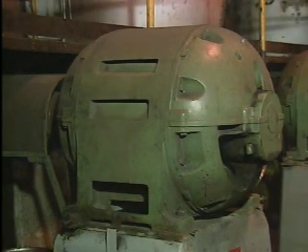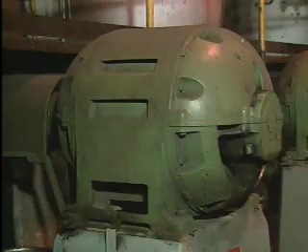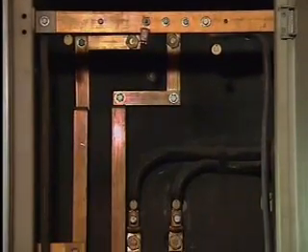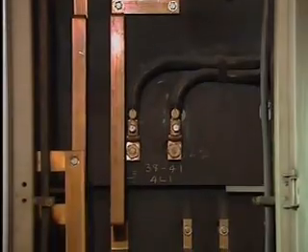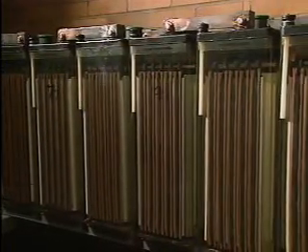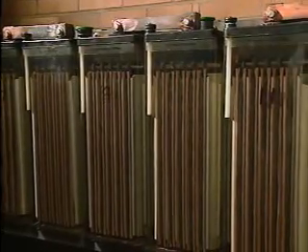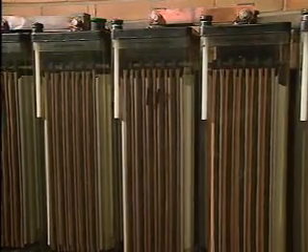Another type of electrical hazard is associated with backfeed. When backfeed occurs, a circuit is energized but not from its normal source. For example, a circuit could be set up to be fed from its normal source under normal conditions and from a battery under emergency conditions. Even if the circuit is disconnected from its normal source, it could still be energized from the battery.